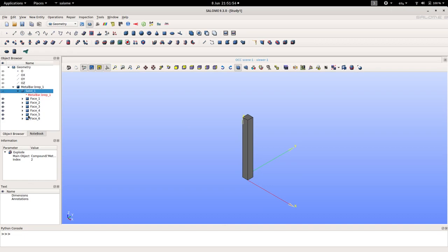But these kinds of equations can be solved only if boundary conditions are applied, and these are indeed the boundaries. So we made clear what the domain where we will apply the equation is, and we made clear what the boundaries where we will apply the boundary conditions are. So now that we did all of this, we can just go ahead and mesh this geometry.